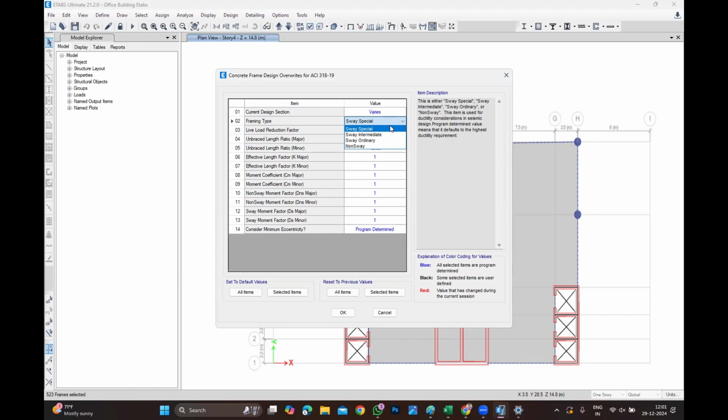Or else I can design the building as flexible. This mostly happens in oil and gas projects. There the specification is mentioned very clearly: you need to consider the building as blast resistant. Then blast resistant is what? If the column, say for example, is 400 by 800, it becomes 800 by 800. It's so bulky, so rigid, because it's made for blast resistance. You have to. There's no other way.